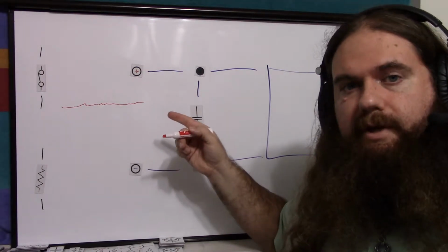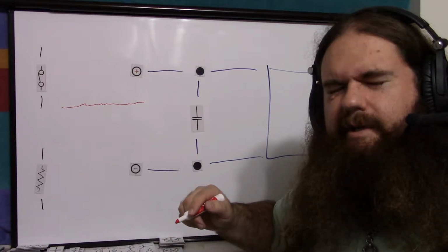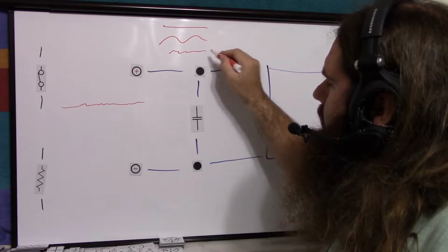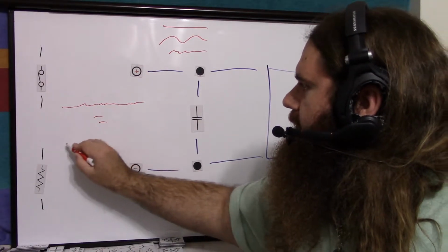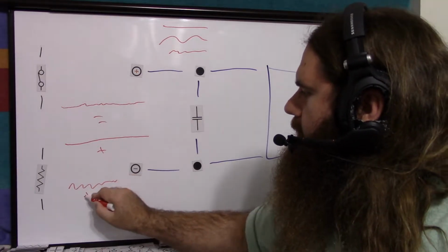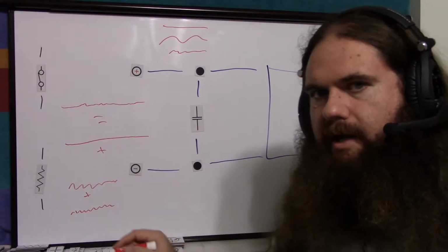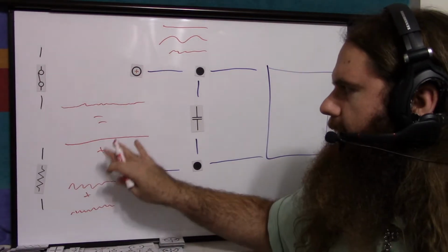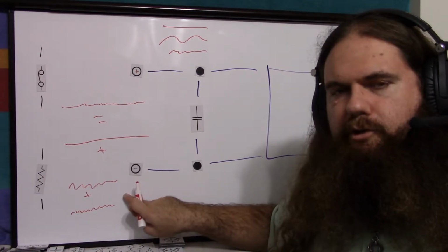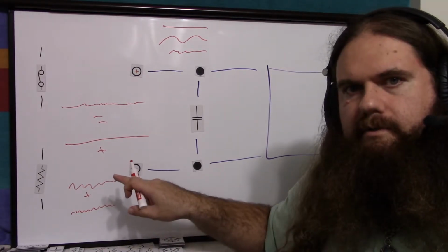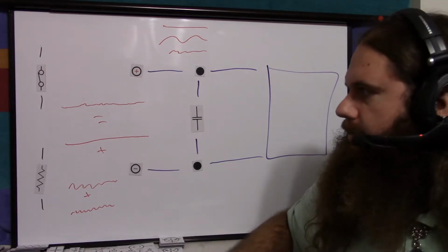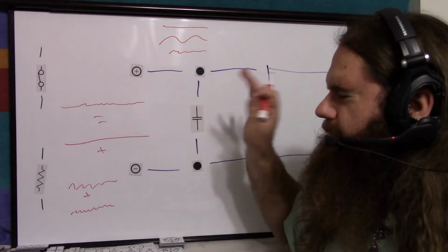Well, the bias of the Fourier series is the lowest frequency there is, isn't it? It's a frequency of 0. It's a line. And then you've got this, and then you've got that. So this equals this plus, let's say, some of this plus some of this, with different amplitudes, different phases. Imagine you have this nice low frequency horizontal line and then these super small, super high frequency little bits of nonsense that have gotten added in. So a low-pass filter allows the low frequency to pass and filters out the noise.